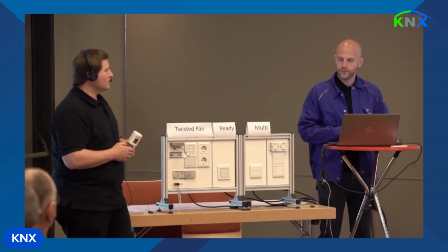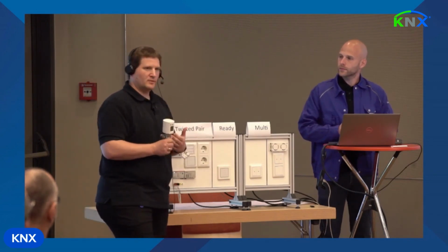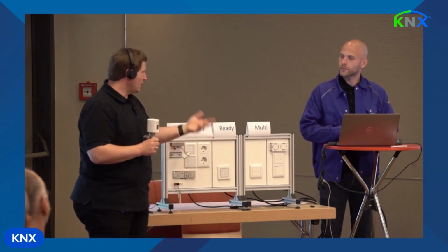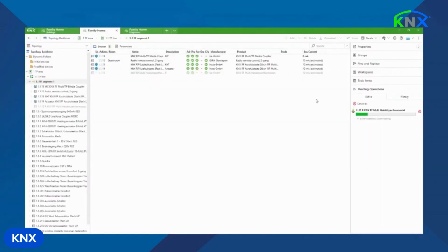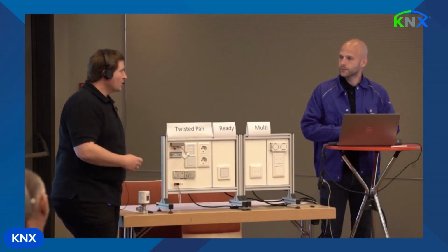Yeah. Why this took so long at the beginning is because ETS now woke up the SLE device. In contrast to the remote control, which you had to wake up manually, ETS has sent out some wake up frames for the SLE device. Wake up, I want to configure you. So I didn't activate the programming mode again. This is now all controllable by ETS, and it's the proof that these devices are battery driven, energy saving, but still listening on the bus.